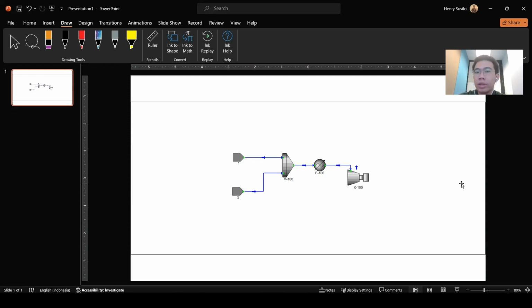This is what makes EO modeling different from SM, because in SM we will solve the flow sheet incrementally for each equipment. Each equipment will have its own model. However, in EO modeling, we will solve the entire flow sheet as one whole equation.